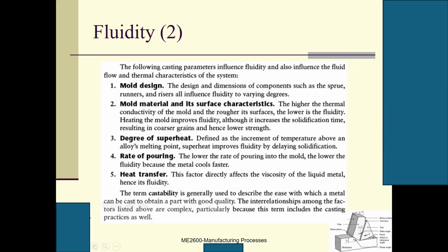The following casting parameters influence fluidity and also influence the fluid flow and thermal characteristics of the system. Mold design: the design and dimensions of components such as the sprue, runner, and risers all influence fluidity to varying degrees. Mold material and its surface characteristics determine the cooling rate. Then the degree of superheat. Do you know what superheat is, guys?